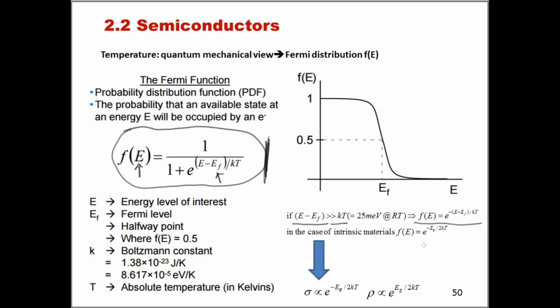And so in the presence of a semiconducting material that has a valence band and conduction band, with the Fermi level, as we said, more or less at midpoint, this difference E minus EF is generally of the order of half the band gap. And that's why here we've simplified our formula even further and wrote it down basically in this way.